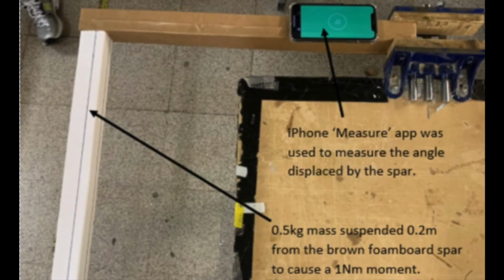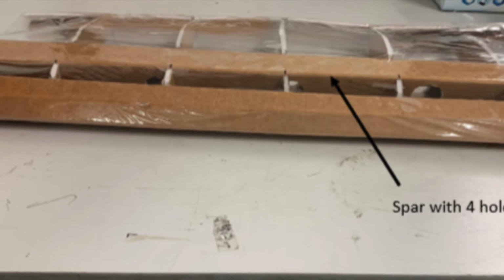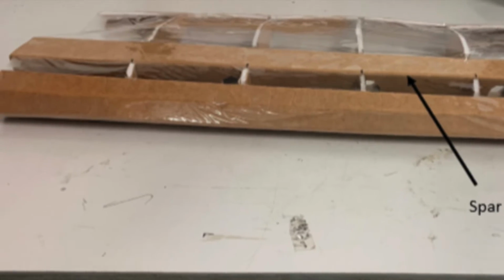Upon testing the spar with no holes, the measured torsional compliance was 1 degree, whereas the spar with 4 holes had a torsional compliance of 3 degrees. As the angle deflected in the lab by the 4-hole beam was within structural requirements, whilst minimizing mass, the 4-hole beam was chosen to be in the final wing model.